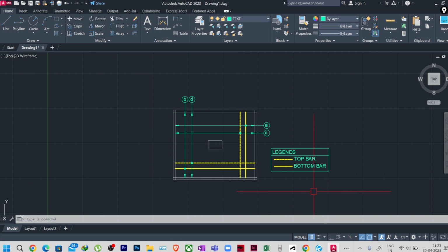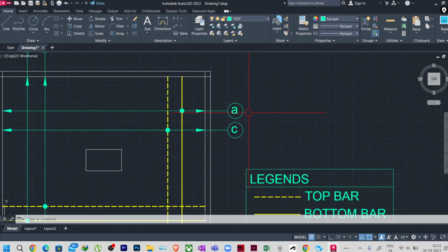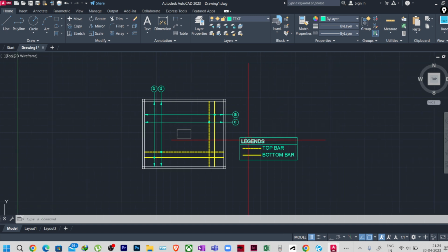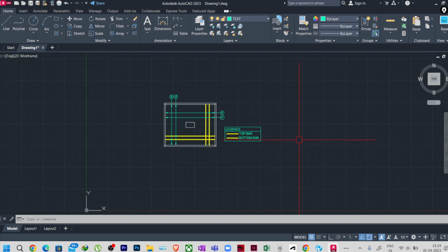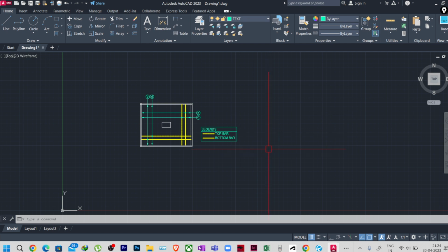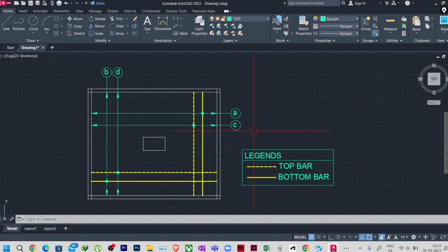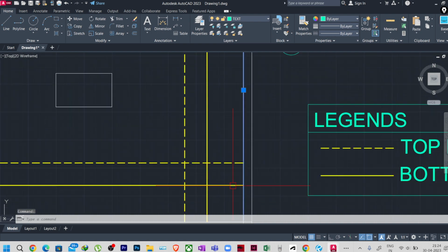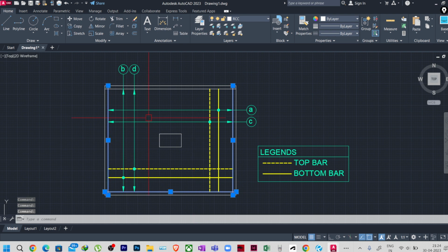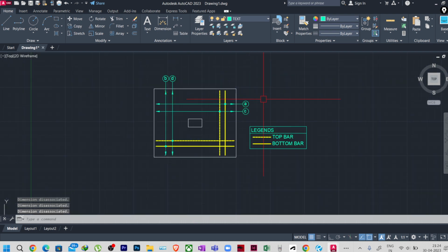Okay, we will provide the bar and spacing, or directly you can also write here, like this bottom bar is suppose T16 at the rate 200 center to center. But in that case, if it is one foundation it is okay, but when you have different types of foundations, means different sizes, different thickness, it is not required actually. In that case, you can give this ABCD and you can give a schedule here. In which schedule, by writing the bottom foundation mark, you can provide the spacing and bar mark. Fine. So these lines are not required anymore, you can just delete it.